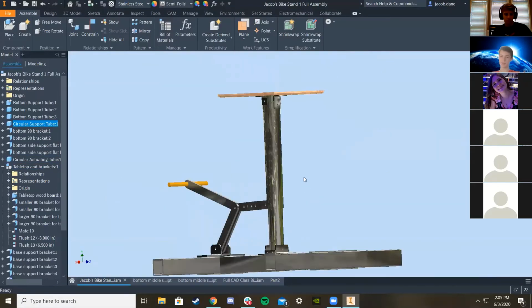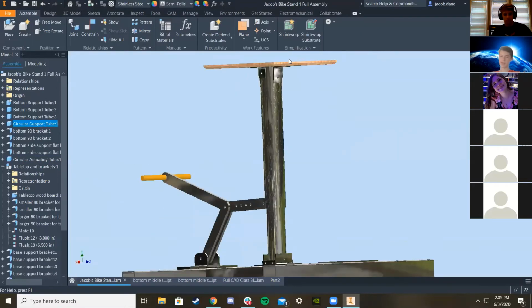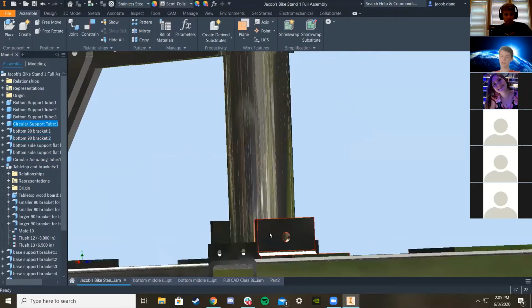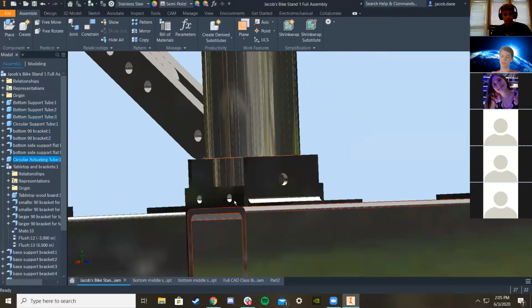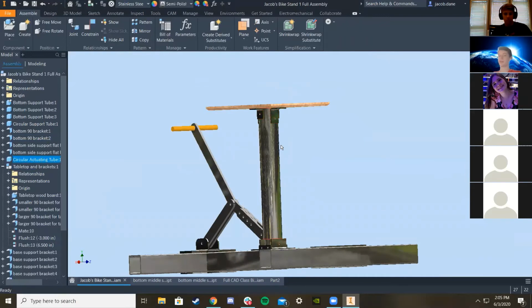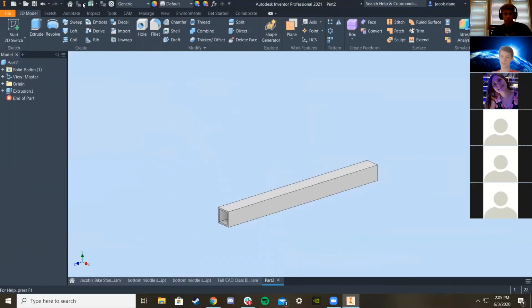And to do that, we basically just have an extra length. So we chose 12 inches. That just means we have to make this inner tube a little bit less so that we have room to put all the bolts in up here. And as you can see, we will have brackets here. So when it's all the way down, we will have brackets here to rest it. So there will already be a difference. But just to be safe, I'm going to add a little bit of tubing to make sure that all these bolts are clear. So that's just something to think about as well.